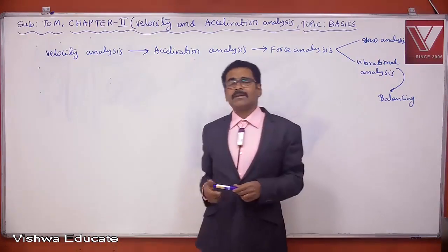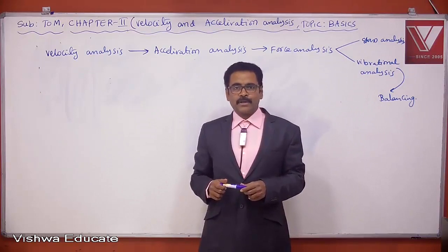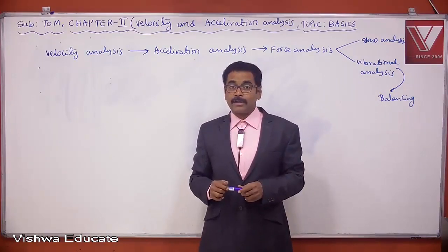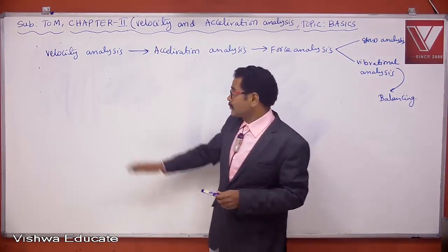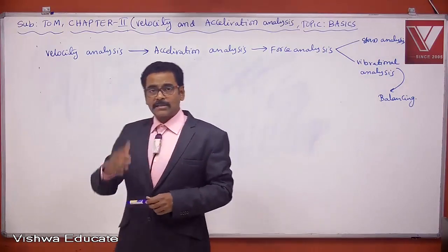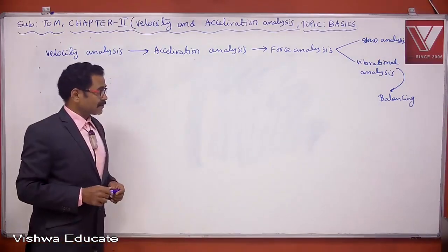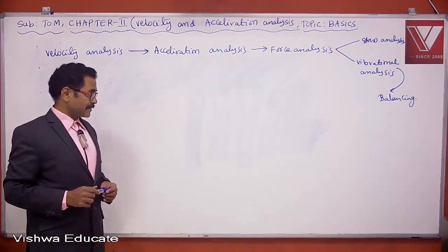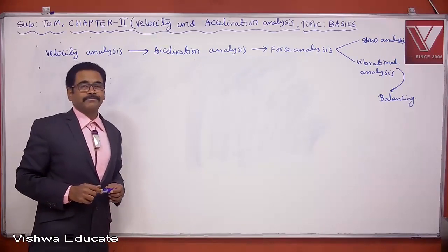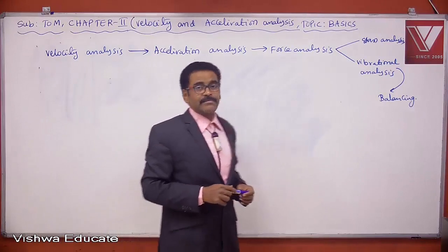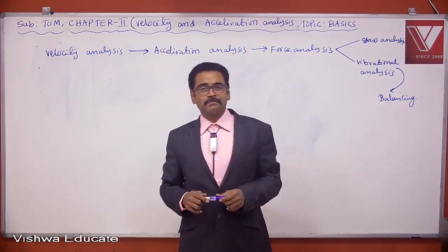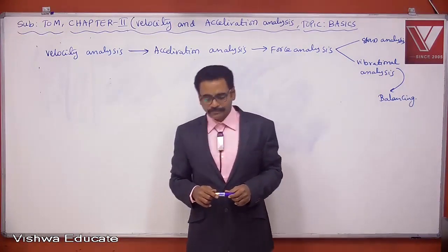So a question came in IAS on sequence. What is the sequence of analysis of a mechanism? Like that they asked. So first velocity analysis, then acceleration analysis, then force analysis, then vibrational analysis, then balancing. So this is the sequence of analysis of any mechanism. Okay?